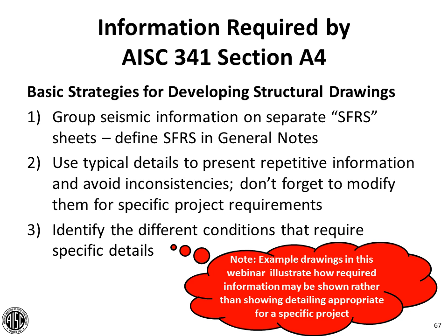And in the general notes, you can define what the seismic force resisting system is, and then use typical details to present the repetitive information, and in that way avoid inconsistencies.